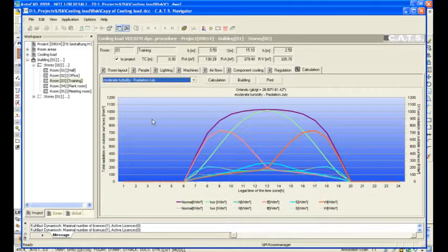In the drop-down menu, we select Solar Radiation. The purple curve indicates the maximum solar radiation of a surface to the sun. The green indicates horizontal surfaces. The light blue is north exposure, pink is east, south is turquoise, and orange is west.